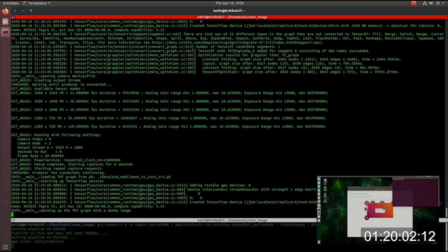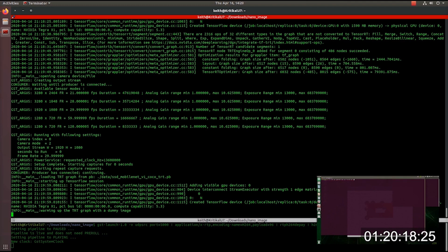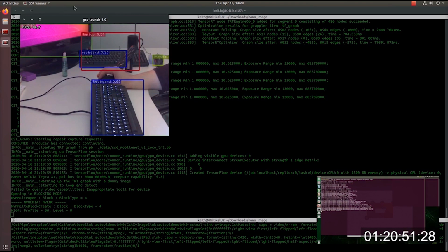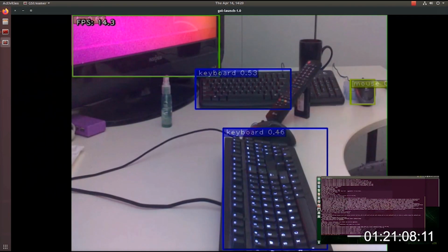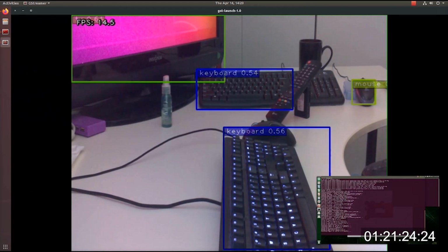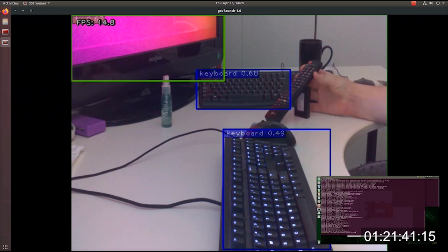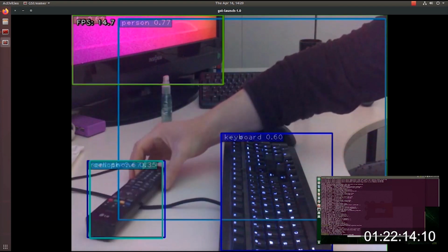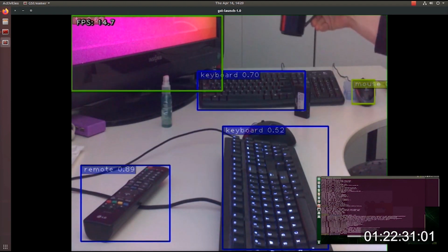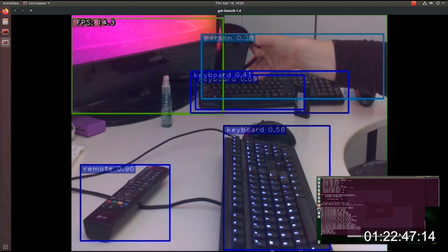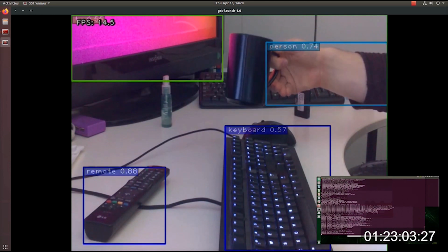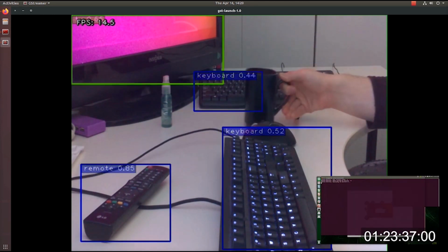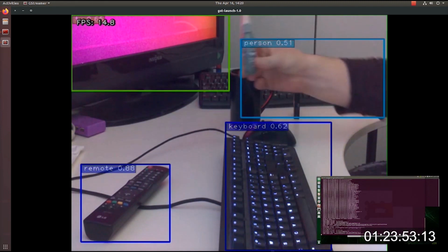So at this point, our Yocto install has gone without a hitch. We're just about ready. Boom! TensorFlow running on a Jetson Nano in under 10 minutes. And just like that, we've got an Edge AI neural net set up, doing what it does best, smart object recognition. The real magic here is that we've built TensorFlow into the Yocto disk image that we make available to customers that are building with the Gumstix Jetson Nano series.